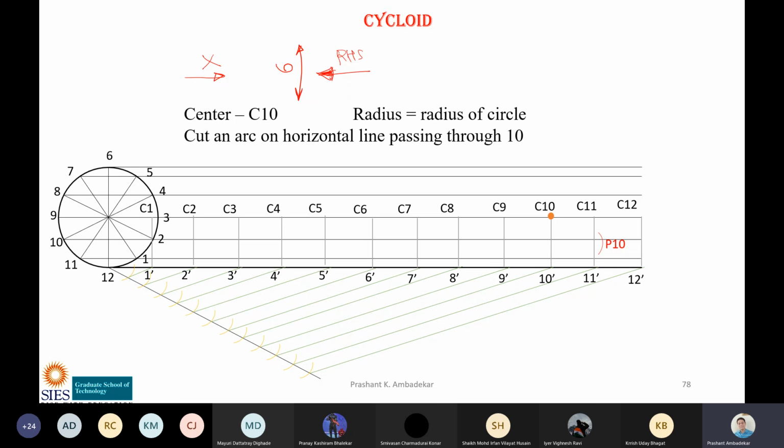Another thing that you have to remember here is the arrow. The arrow should be closed and filled. So what is an open arrow? Open arrow is this. This is the open arrow. This is the closed arrow. And this should not only be closed, it should also be filled. So how will we fill it? We'll fill it like this. When you are drawing it on paper, it will not be that big to fill it like this.